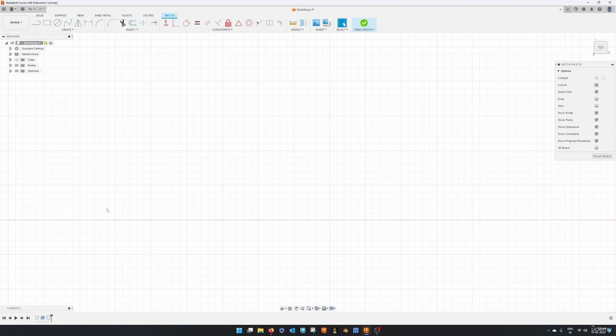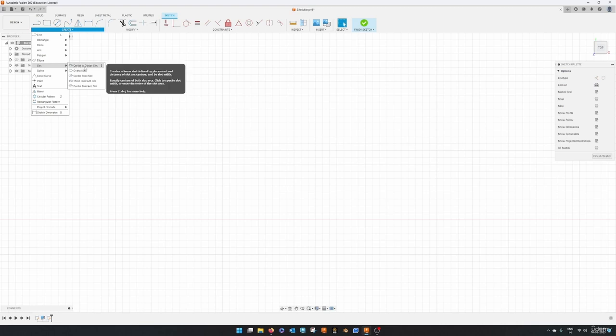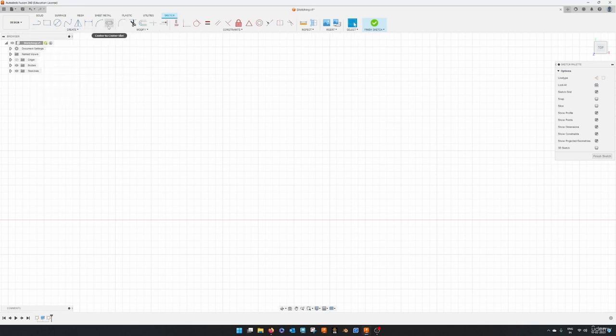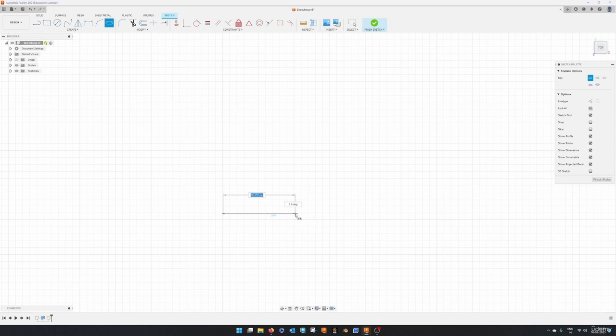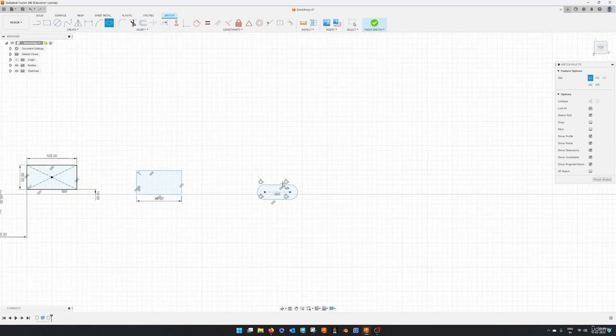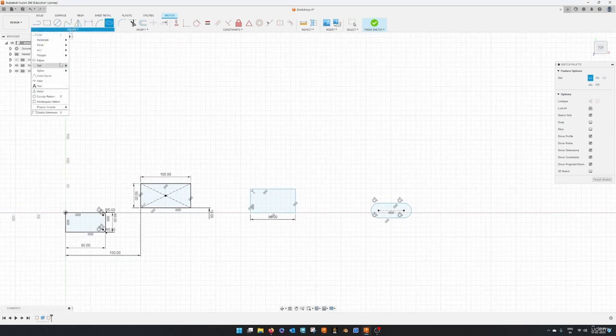And also here's another tip. Let's say we have this slot tool. I'm using this more often than not, and it is not available as a shortcut over here. What I can do is go to the tool, and these three dots are highlighted over here. Click on this and pin to toolbar. So now this tool is available for you to use as a shortcut. It's a very simple tool. You give one line, one point and another point, and you can make a slot like this. So you can explore this by yourself. These are fairly simple tools.